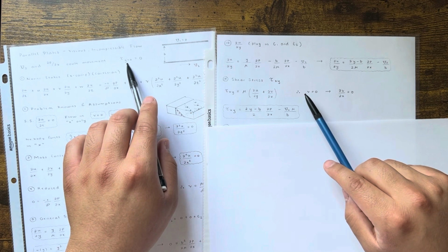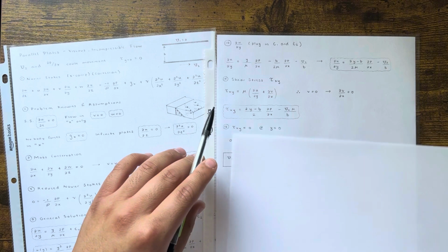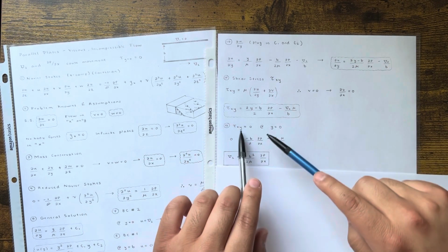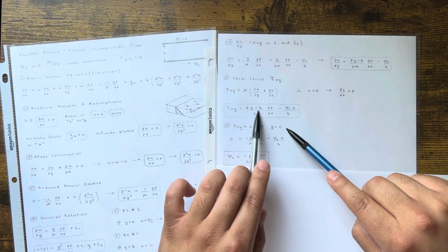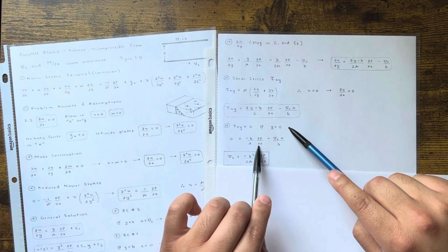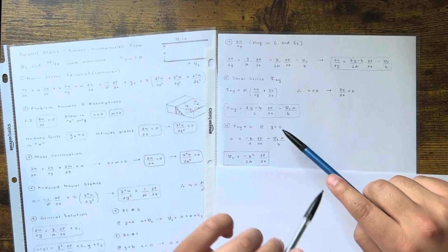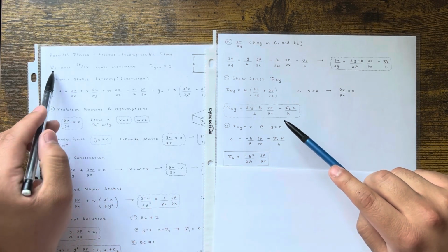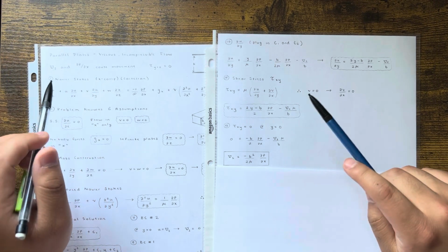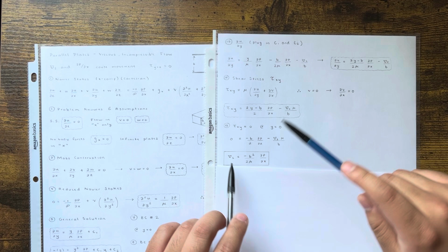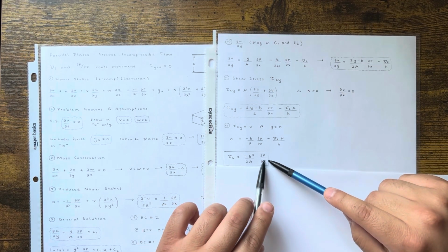Tau is 0 at y equals 0, remember from the beginning? So when I do that, tau is 0 at y equals 0. Well, that's 0, so it's just negative b over 2, delta p over delta x, minus u2 mu over b. They wanted this in terms of this, or it could have been this in terms of this, whatever the difference is. You could just solve for one or the other. The problem was a little confusing if you read it, but I just solved for u2 in terms of delta p over delta x.